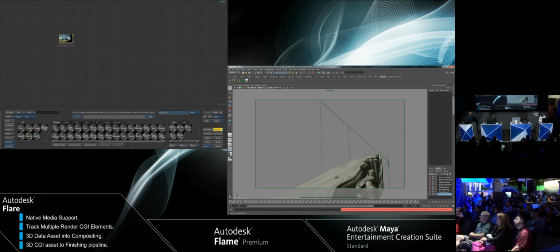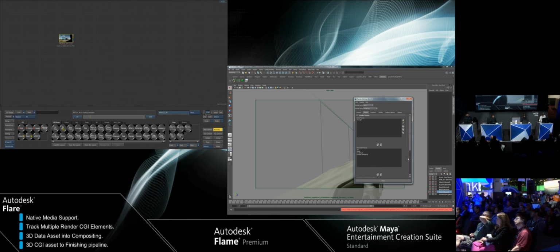So what I've done is I've gone ahead and I've set up a few different versions. So we've got a version without the rocks falling, a version with a rock, kind of dropping off a big rock, and then we have a third version that basically has some grass and some smaller pebbles. These layers or versions also have render passes associated with them. So if we bring up the pass system inside of Maya, you can see that for each one of these versions, we're rendering out ambient occlusion, depth, motion vectors, and normals, and that information will get passed back over to Will, to Flame, I should say.